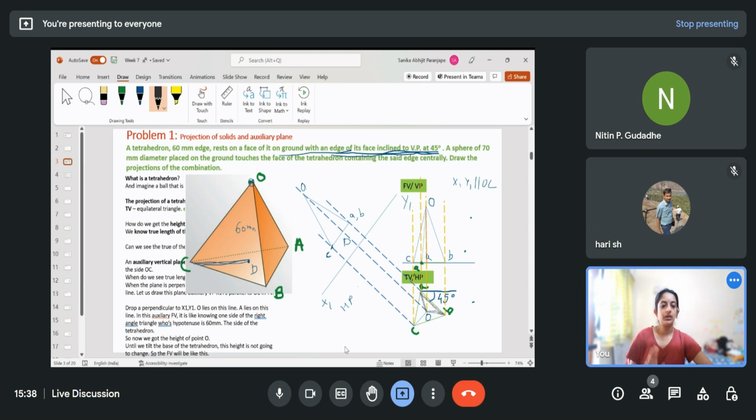Okay, so now, like I explained here, if this is my plane and I have a sphere sitting here, I could see the center of the sphere on the angle bisector of this angle, because what I was seeing was a true angle. So now I have taken this auxiliary plane view where I can see the true angle of this plane OAB with the horizontal plane.